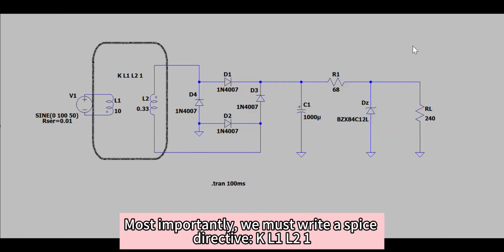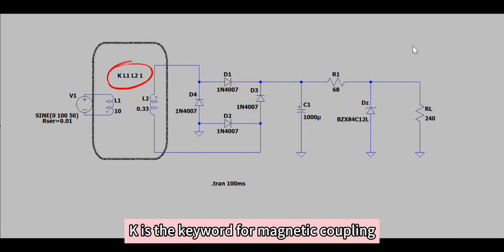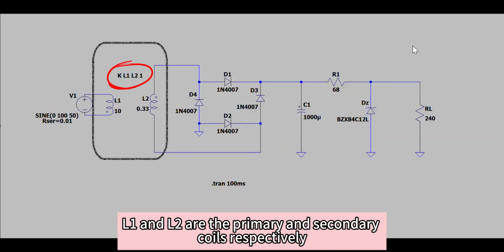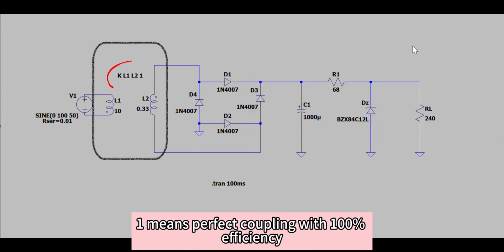Most importantly, we must write a SPICE directive, K L1 L2 1. This directive tells SPICE to couple L1 and L2 with perfect magnetic coupling. K is the keyword for the magnetic coupling, and L1 and L2 are the primary and secondary coils respectively. And 1 is the coefficient of coupling. 1 means perfect coupling with 100% efficiency.